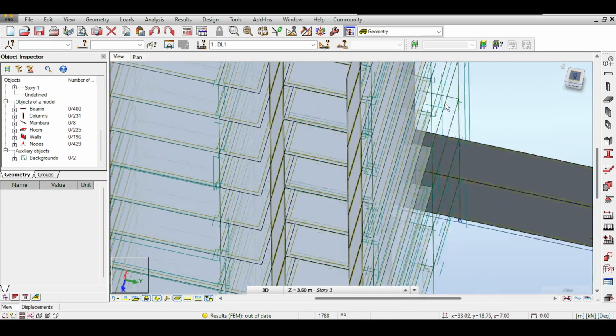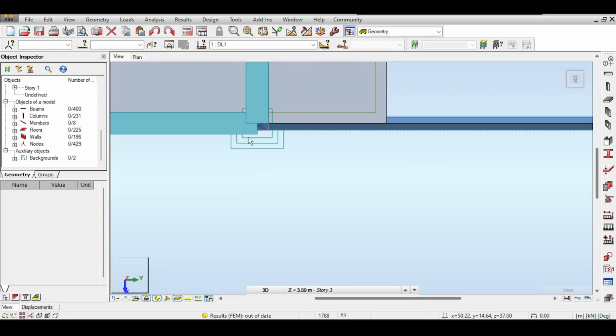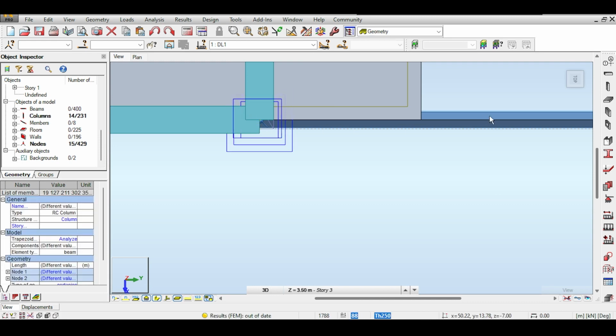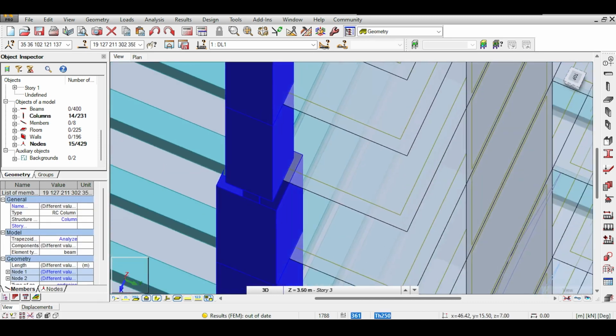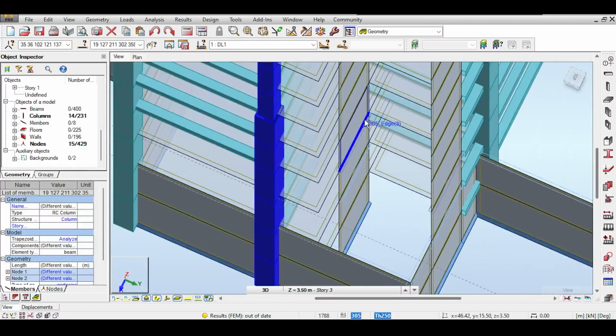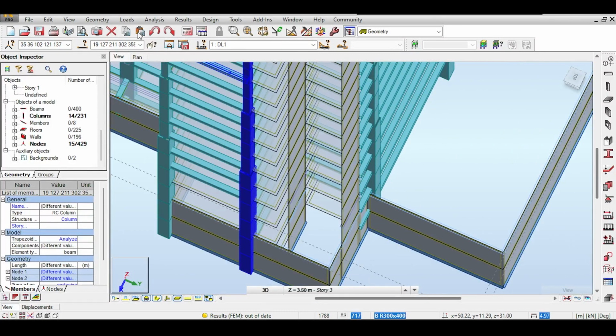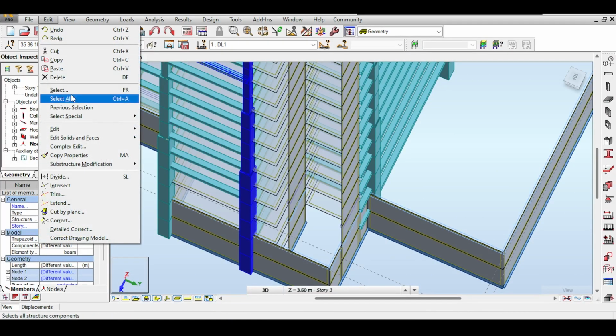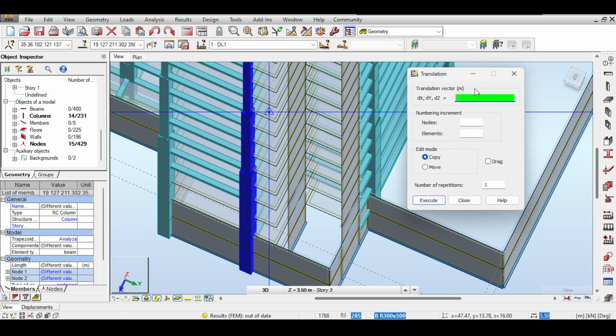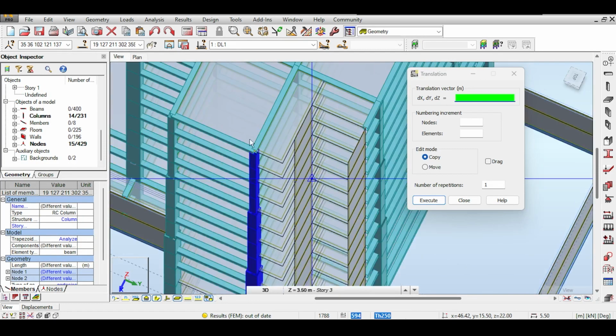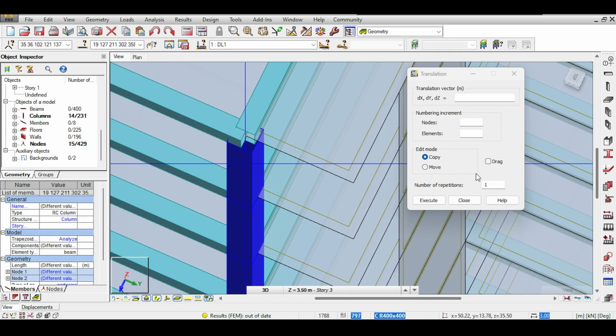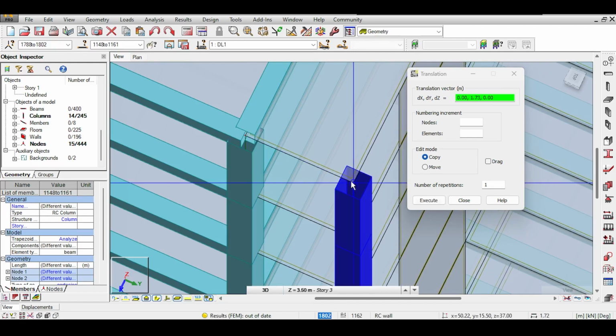So how would I move it without moving the beams? Well, simply said, I cannot. So how will I achieve my mission? Well, that's even easier. I'll select edit, move or copy, and I'll copy only. See? And then I will delete the original. So I'll copy only, and then I will just delete the original. It's as simple as that.